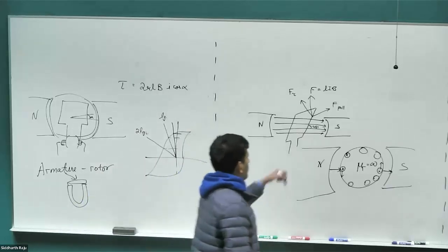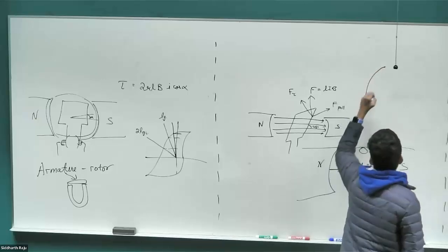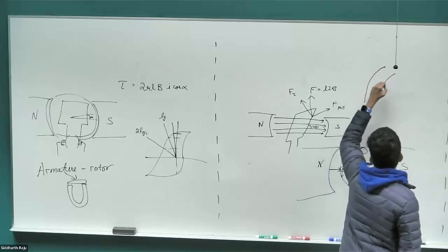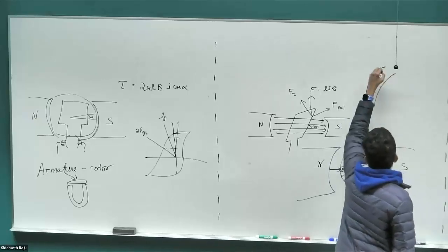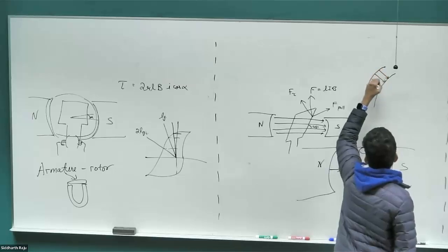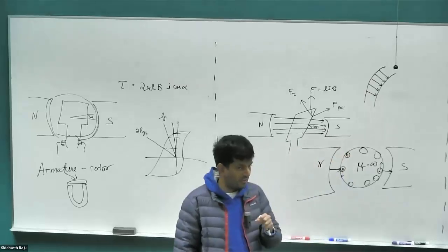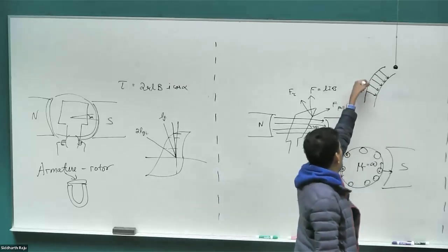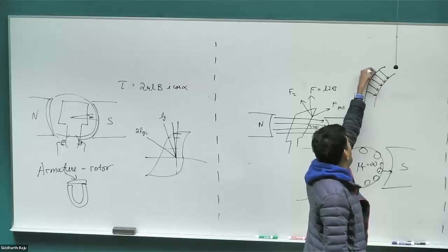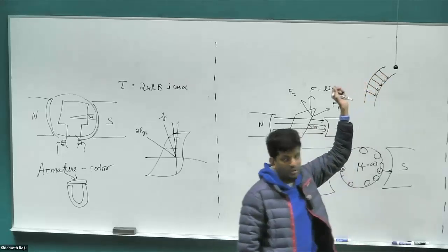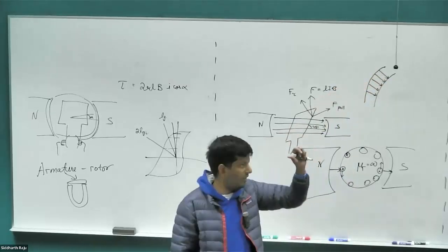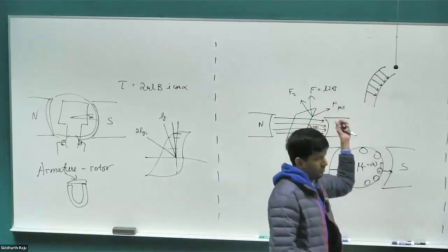Whenever you have two surfaces, let's say I had a surface like this, the least reluctance would effectively be the shortest distance, right? The point where the gradient is going to be your minima. So it is always going to be the perpendicular direction from one surface to the other surface. That is where you're going to have the path of lowest distance. Smaller the distance means smaller the reluctance.